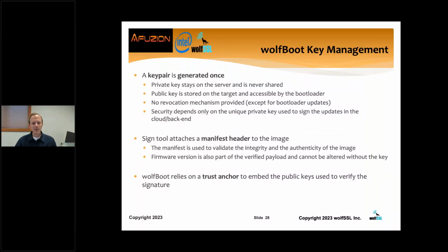So for key management, like I mentioned, we like to make this easy for you. So up front, a key pair is generated once. The private key will stay on the server side, typically is never shared. That might be held in an HSM or somewhere secure. The public key is stored on the target and is accessible by the bootloader itself. That's what's used to verify the image.